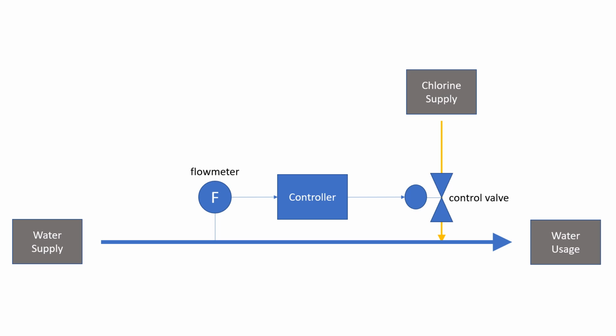Its main purpose is to provide correctly chlorinated water supply to the user, by dosing chlorine into the main pipeline proportional to the water flow. If the chlorine dosage is inadequate, then there could be some germs left in the water. On the other hand, too much chlorine could be dangerous for water users and increase corrosion rate of the pipeline, beside increased material costs.